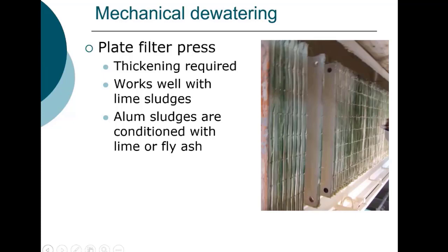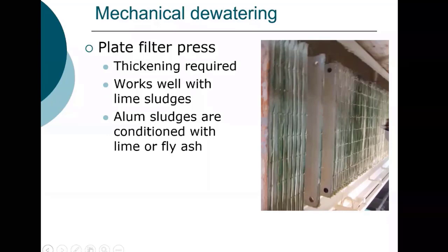Typically, it takes about 20 to 30 minutes of pumping of sludge into the filter press. When it's full, then the pressure is applied at the maximum level, which is typically between about 700 to about 1700 kilopascals.